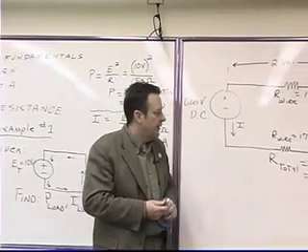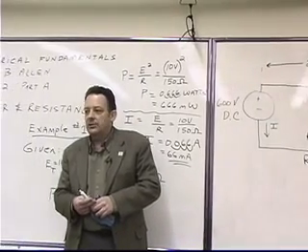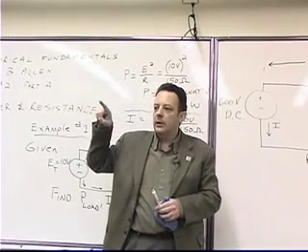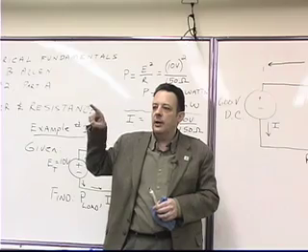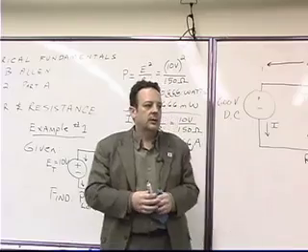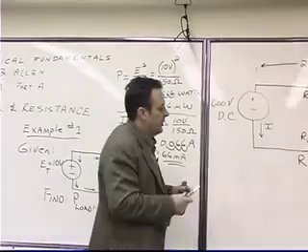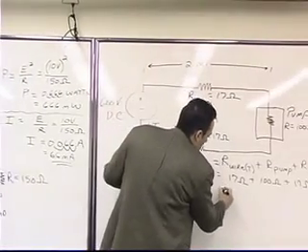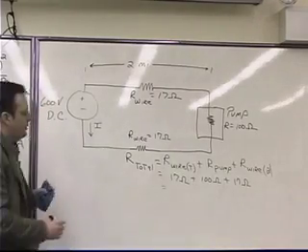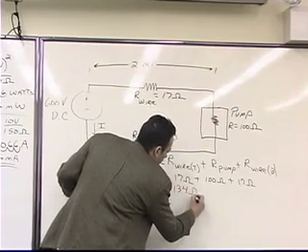And they'll usually ask it something like this: the current flowing in a series circuit is always the same in every component, always different in every component, sometimes different in every component, or really can't tell. Of course, A would be the correct choice, always the same in every component. So if we add these up, what do we get for the total resistance of the circuit? 134 ohms.